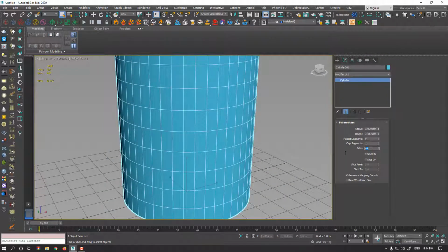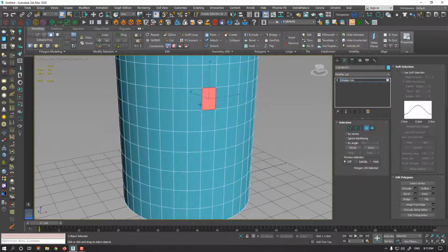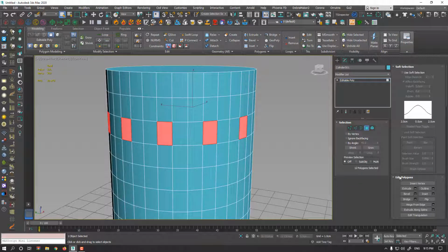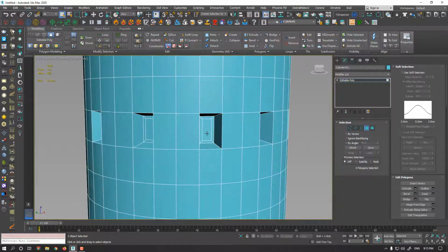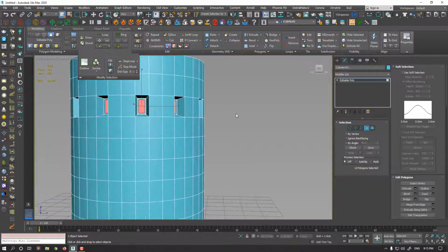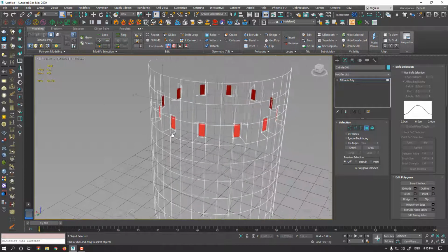So usually we need some standard subdivision, something like 36, 72. Alright, now it is perfectly selected, and I'm starting something like bevel. Okay, and inset. Now imagine you want to select everything similar to your current selection. You just need to select one sample and click on similar. As you see, everything similar to this current selection is selected fine. In some cases it won't work perfectly, but usually works very fine.